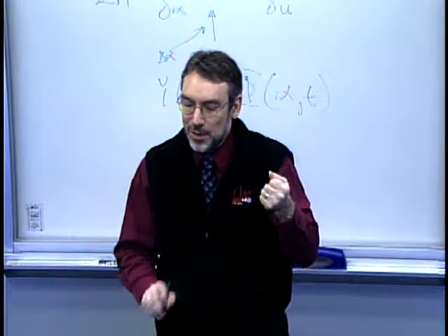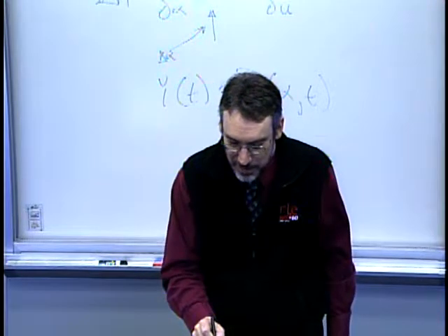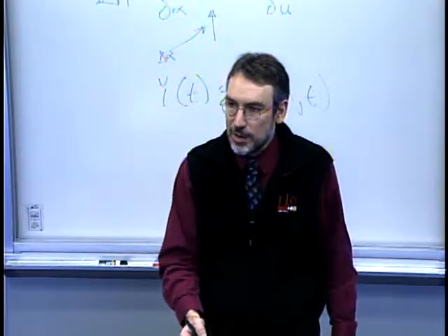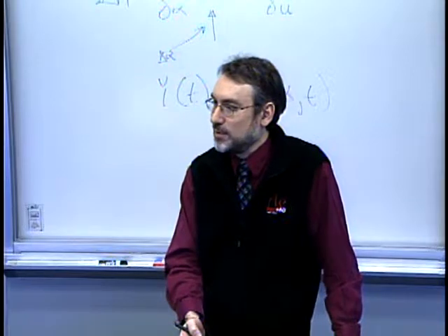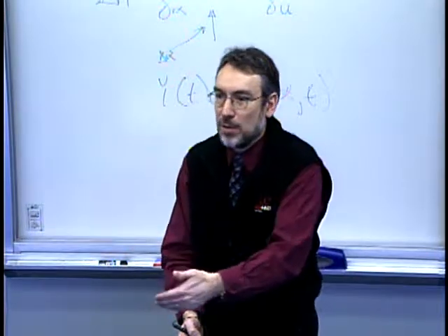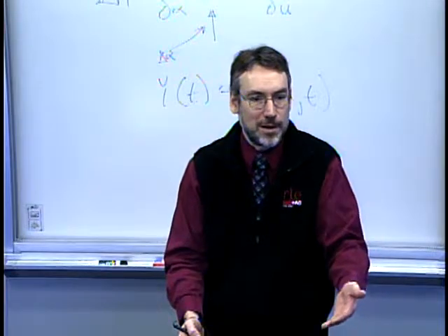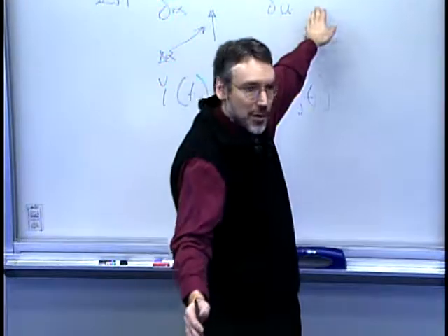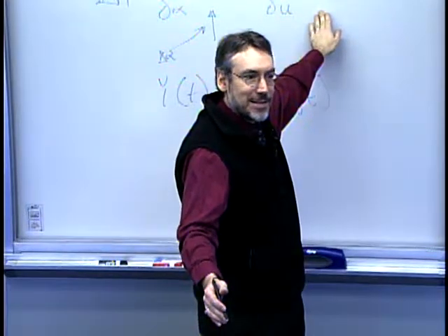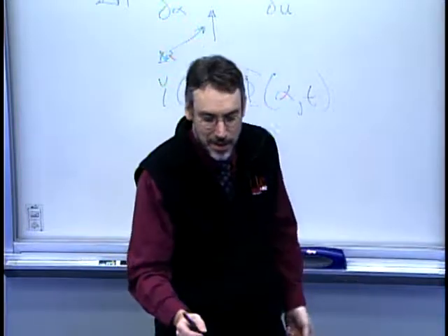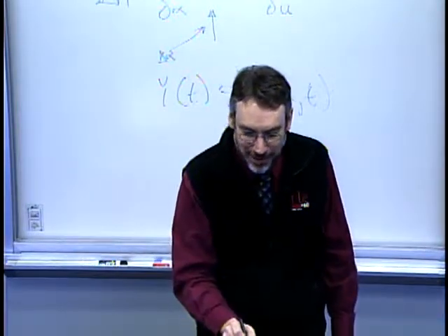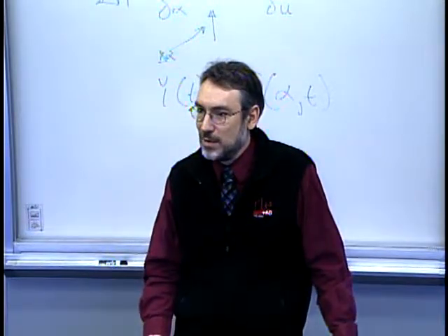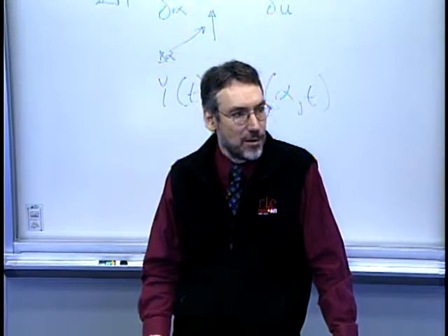And the natural occurrence then is that over time, as you have learning about your process and manufacturing system, you're generally squeezing out these deterministic sources, right? Something was repeatable, systematic, and therefore you can come up with strategies either to eliminate it or to compensate for it. Maybe you have to have a control strategy that recognizes that source of variation and keeps squeezing it out. And what you generally are left with are these random components, hopefully in a very nice narrow band. But we still need to understand and model those.